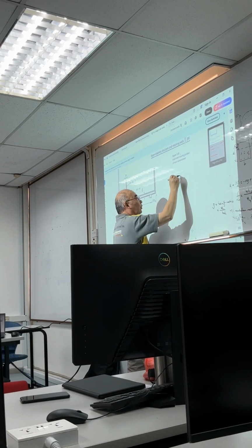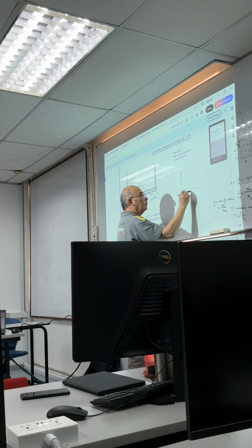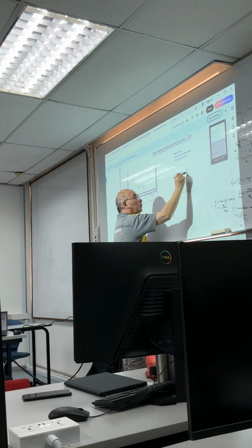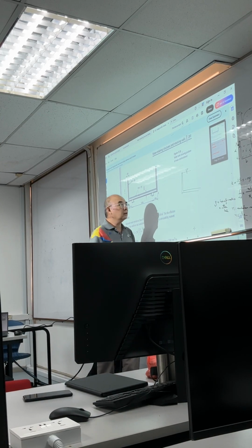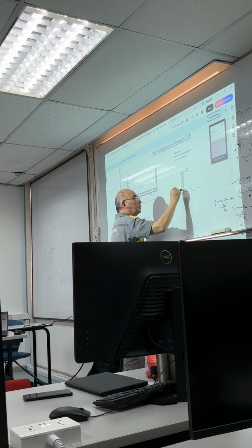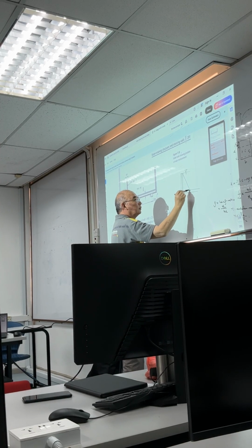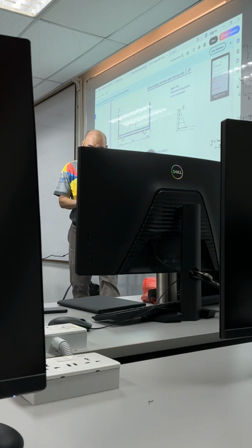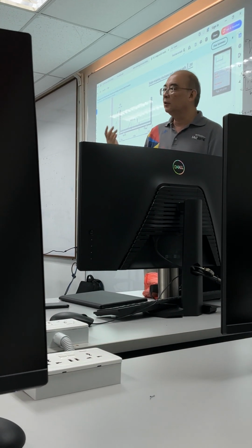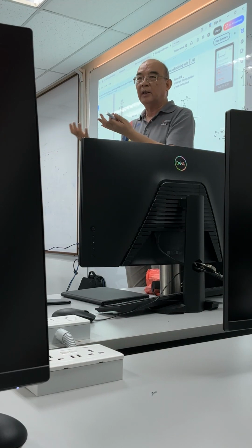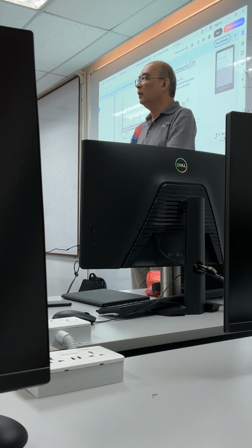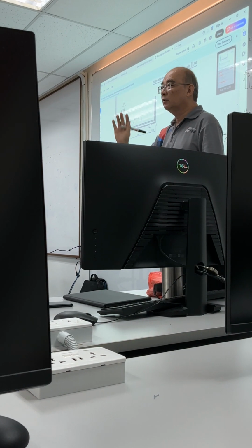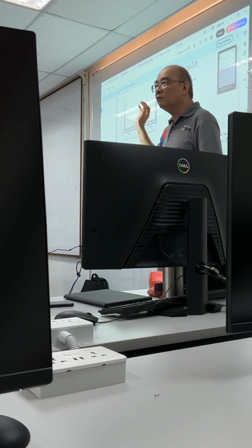How do we calculate the... let's say I have this wall here, this slab here. So what we have is the water, and then the water will exert horizontal load. In your RC1, basically you design for vertical load, right? Your slab, your beam, your column, your footings, and so forth. This one is the lateral load, the lateral load from the water.